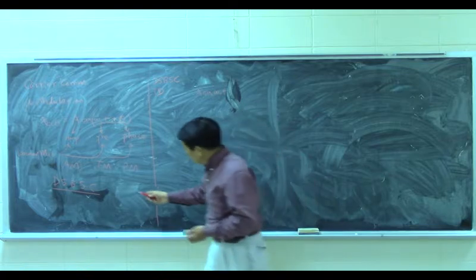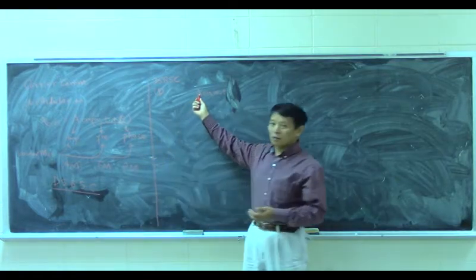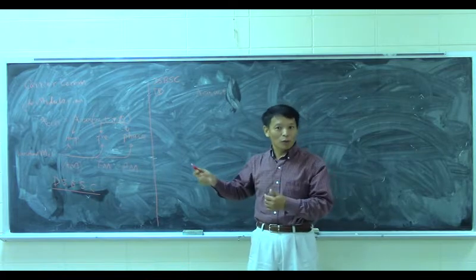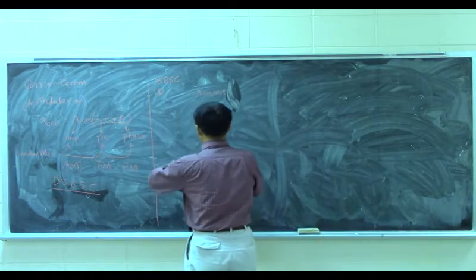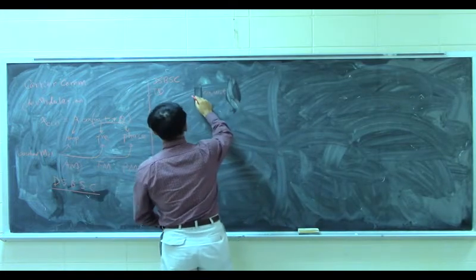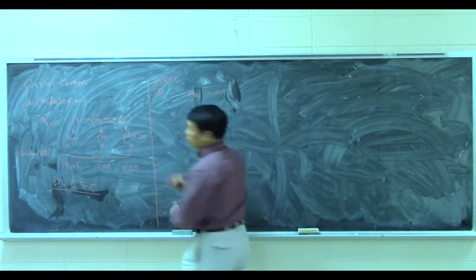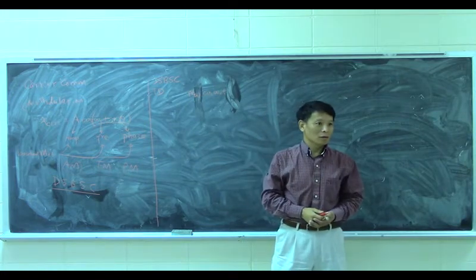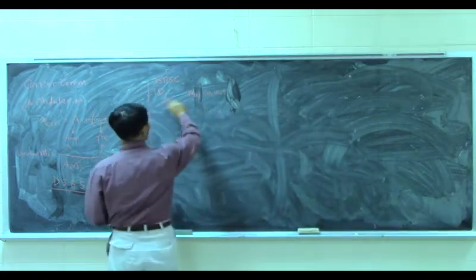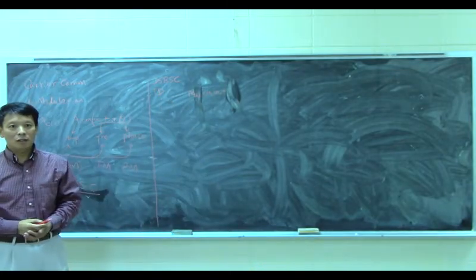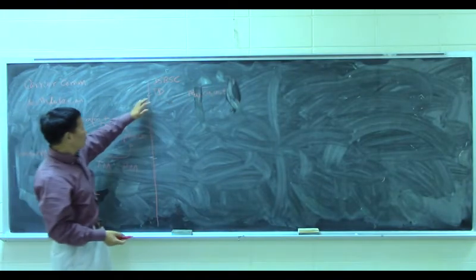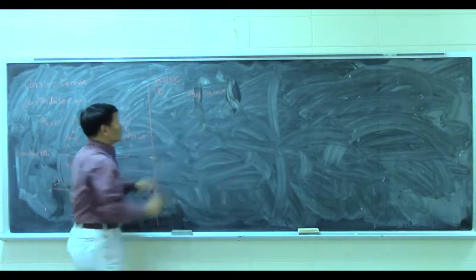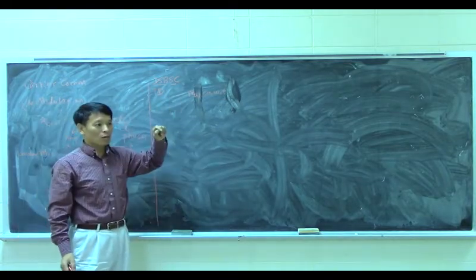So we said we want the baseband information to be in the amplitude. So the very straightforward way is we just change this A to m(t). Now the baseband information is in the amplitude. Yes, that is the time domain representation for double sideband suppressed carrier. So we are going to explain why it's called double sideband, why it's called suppressed carrier.